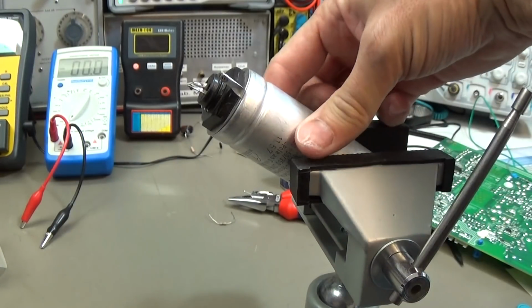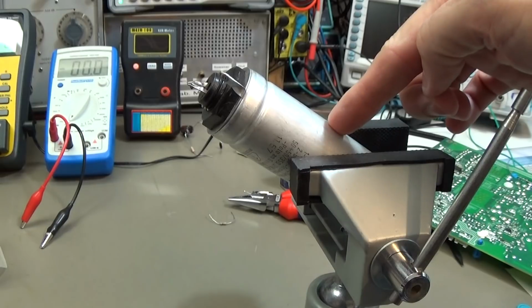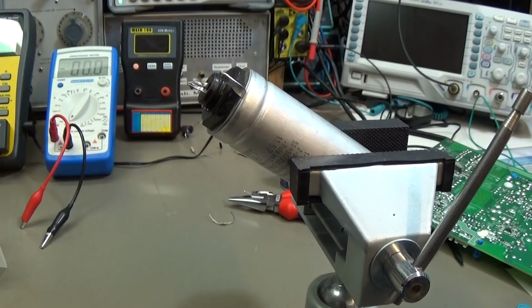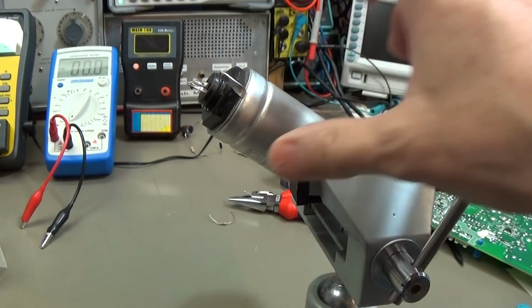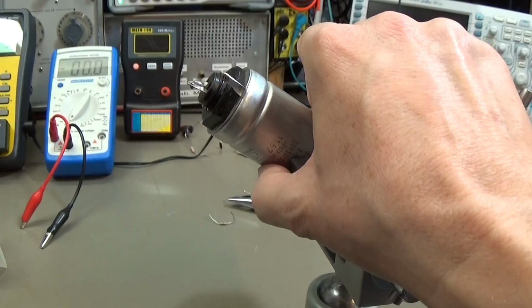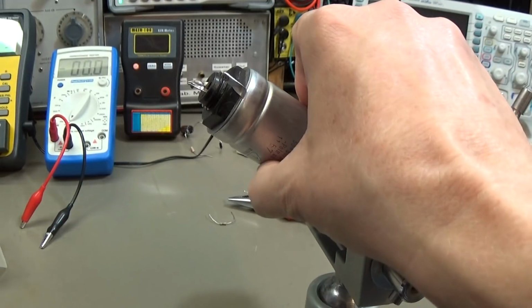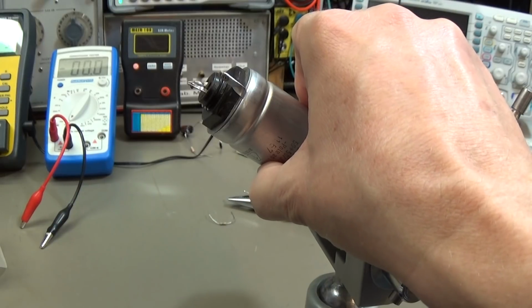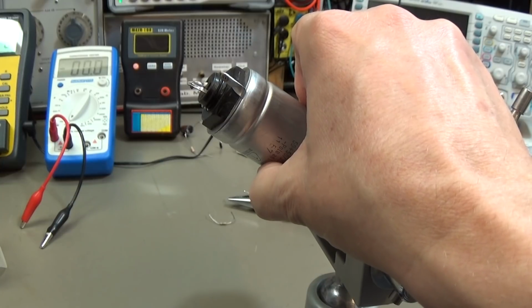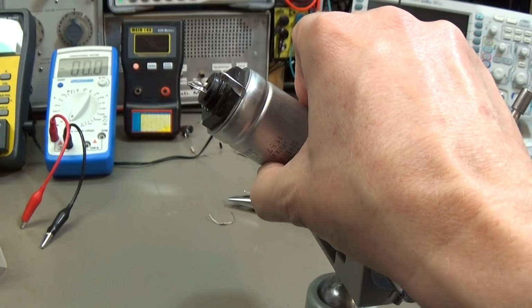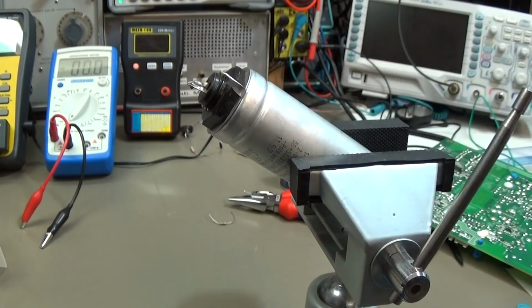I was testing for temperature, because if there is a short, or not really a short, let me simply say a resistor inside which is leaking, then we would feel the capacitor getting warm. You remember that I was observing the indicated power the IT12 is allowed to consume, and we said 25 watt is fine.